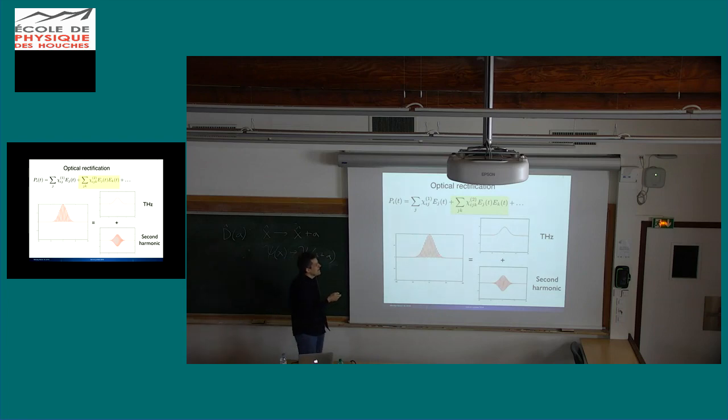And then the idea is if you take this second order response, that's essentially what this is, in a scheme, you can represent that as the sum of two different components. So you have the second harmonic component, which is maybe more familiar, which is what happens if you look at the local average frequency. This is going to oscillate at twice the frequency. But you also, if you average all those fast fluctuations out, you're left with this pulse here that will have frequency components characterized by the inverse of the width of the initial pulse. Okay, so that's going to be in the terahertz frequency range. And so this is what we want to use. We want to throw away this and use this. Typically, most of the time, I think people are trying to get this and throw away that.